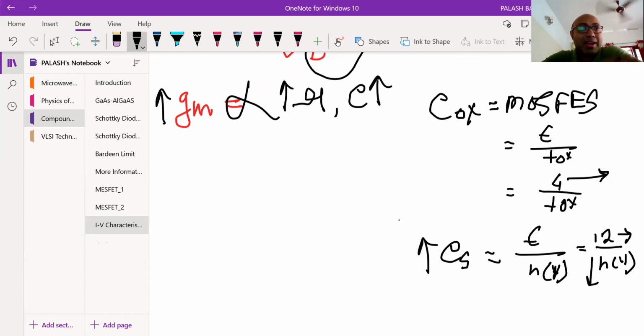So that is one of the great advantages of having GM on this MESFET structure. And here people are not confident to go for silicon. You have a MESFET structure where electron is flowing through the bulk. Now you have a choice. You can make a MESFET structure for silicon, or for gallium arsenide. Definitely for high frequency applications, you will be going for gallium arsenide or a compound semiconductor having high mobility, right? That is the great advantage you will have.